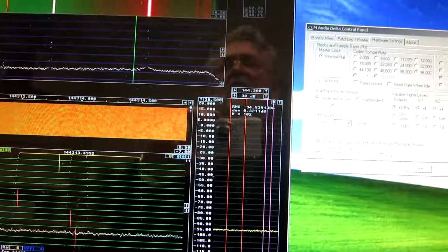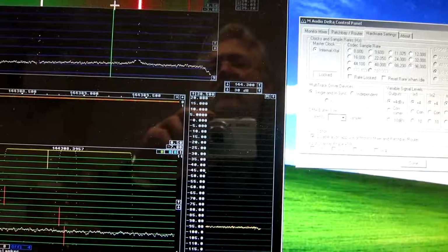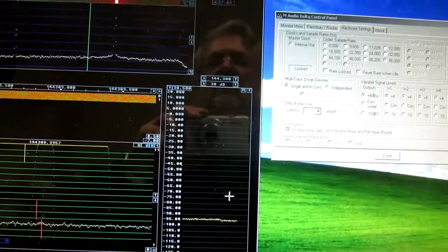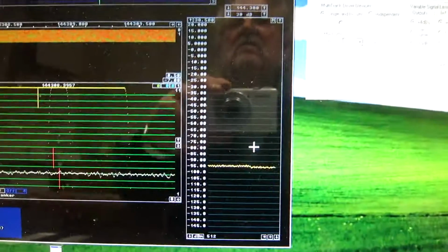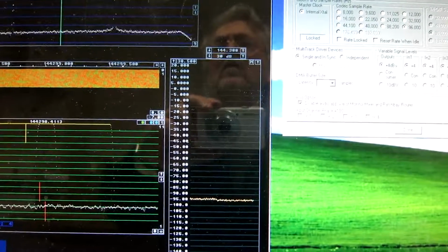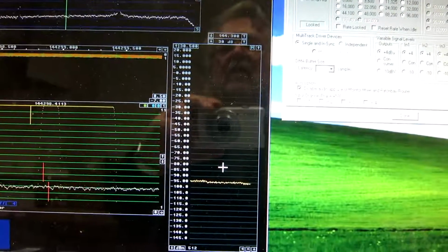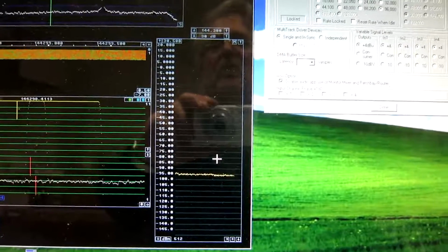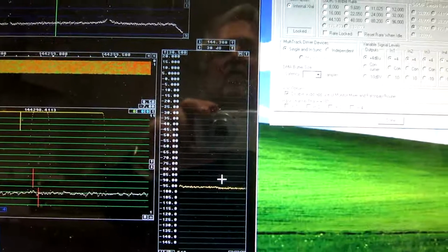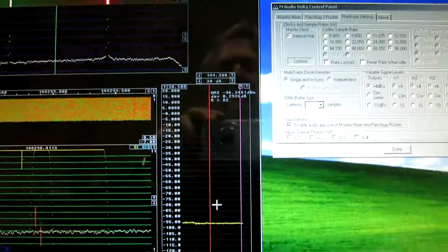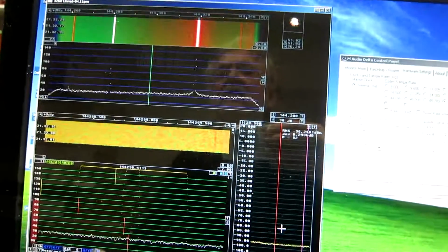And then 10 kilohertz away, it will be here, the noise floor is very much the same. And then another 10 kilohertz down to come to 20 kilohertz. And the noise floor is very similar. So this looks a little bit odd. The noise floor at 20 kilohertz on the transmit side is minus 96.2.